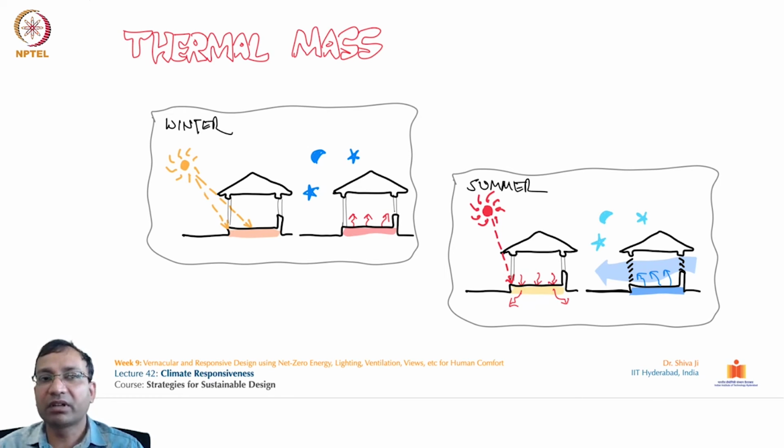You can see over here, this fiberglass insulation has the lowest thermal mass capacity of only 9.2 kilojoules per cubic meter Kelvin. And if you see, water has the highest capacity. So when we have a requirement of thermal mass, maybe we can go for these materials from the top: water, granite, concrete, sandstone, and clay tiles, etc. Where we do not want it, we can go from the bottom up.